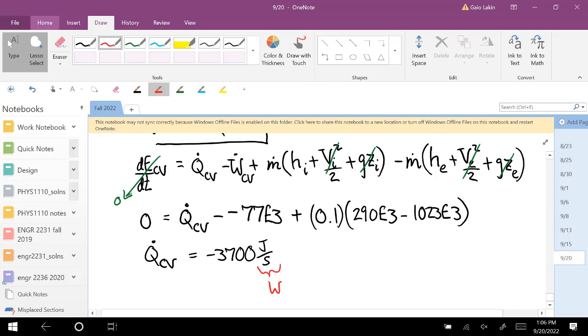And then the last kind. You deal with pumps the exact same way as this, it's just you'll be dealing with liquids. So one thing about pumps, you're dealing with liquids, so we're always going to be happy to make the assumption of incompressibility. With gases you can't do that. But if you're pumping liquid from a lower pressure to a higher pressure, you can do it exactly the same way, except you can make assumptions about the liquid if you need to calculate properties.